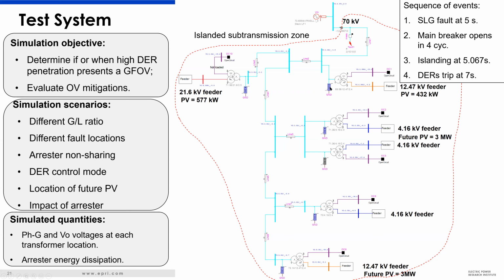The level at which the problem started to occur was 67%, and the overvoltage increased to 1.82. So the arresters started to conduct heavily, and they clamped the overvoltage, but their energy rating exceeded the estimated arrester energy capability, and therefore the conclusion is that at this voltage, the arresters are likely to be destroyed.